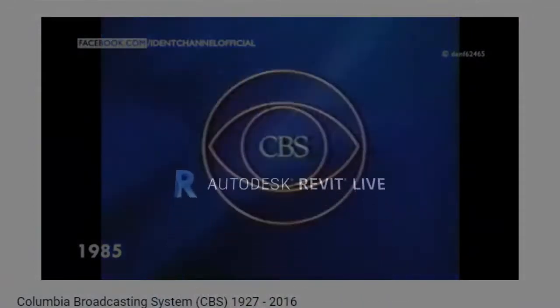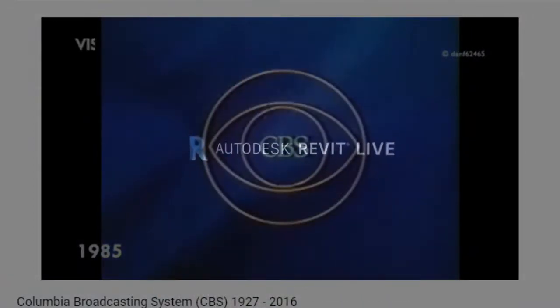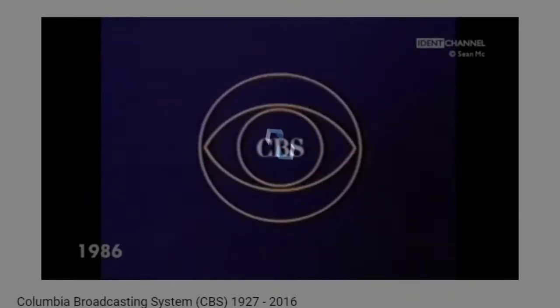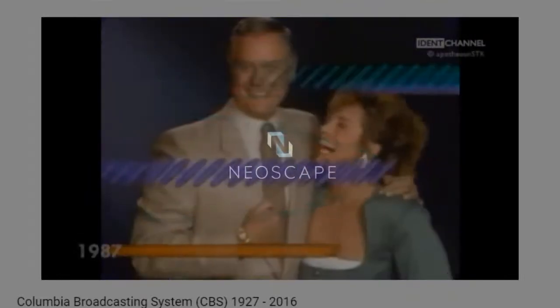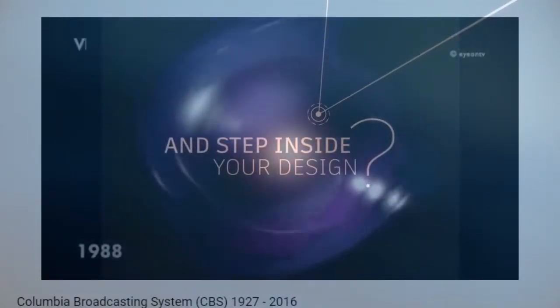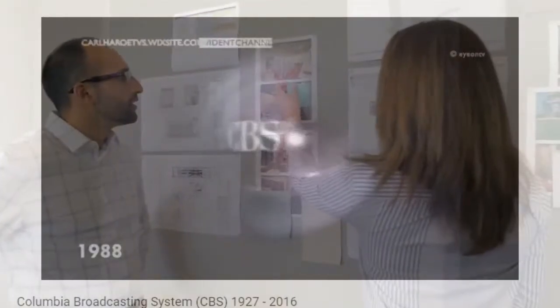All right, so we have this nice slab depression, and it's still in the command. Let's pick on it and take a look at the parameters that were programmed into it. Length Y, length X, and cut depth, which is great, right? So we have an X, a Y, and a depth. Right now it's cut at 3 inches. Let's just drag it bigger here. We have grips, so you can drag it over. Let's bring it to, look at the bottom elevation.